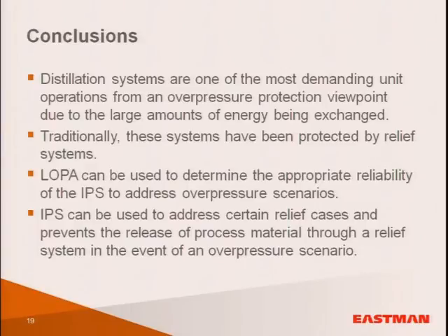So they designed a very large reboiler. So with the 125 psig steam, I had a very large heat input that I would have had to deal with, which made my relief system prohibitively large. So what we ended up doing before we looked at the LOPAs and looking at a SIL2 interlock, we tried to use a novel approach with a pressure relief system. And what we did was we considered the design of a relief device in the steam supply to limit the steam supply pressure to a manageable value.